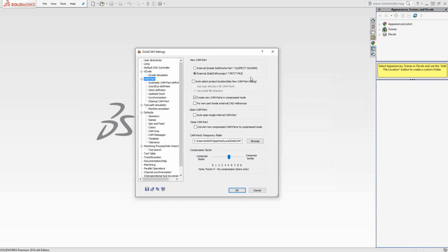Essentially what you've done is you opened up a new assembly file that you can add in your own sketches, your own solids. And that is a separate file for you to work on. You actually work on what we call the design model. It's a perfect copy of the original SolidWorks model. So you can make changes to that model to make the part more machinable if you so choose. And that also maintains ISO 9000 as well.